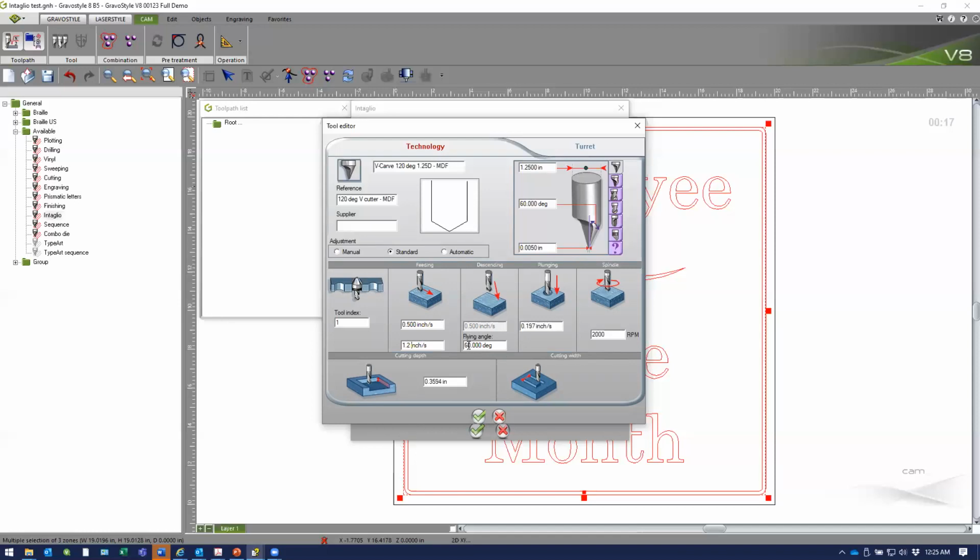For the flying angle, I want to tell this that the angle is 60 degrees. So basically, the descending angle is, as that cutter is entering into the material, what is the angle of half of the tip of the cutter? So that as it's feeding that cutter into the material and indexing it on the XY, it knows what slope angle to set up so that the profile revealed in the edges of the carving is appropriate.